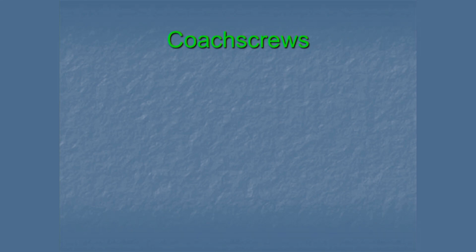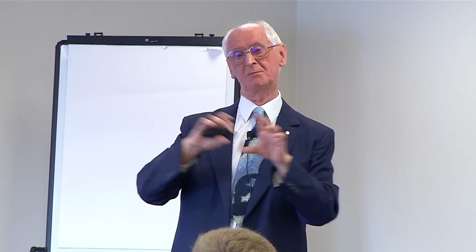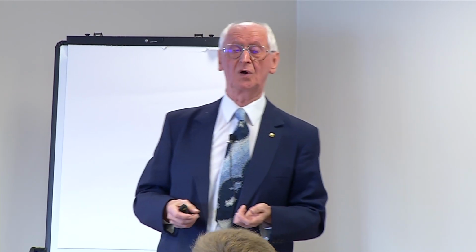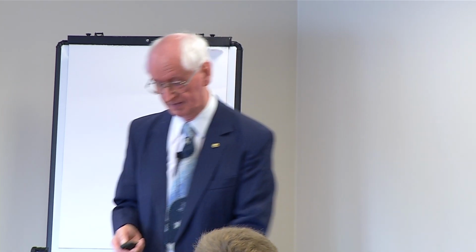And we come to coach screws. Now, coach screws are really useful. I've done loads of projects where you have to put one timber against another one and the timber's against the wall, so you can't get to the back of it. You may also want to join timbers. We've done plywood splicing of timbers, particularly hip rafters, where we would use a coach screw.